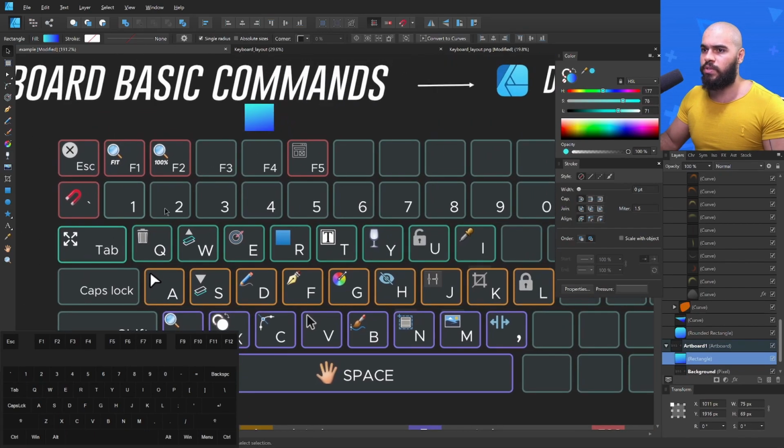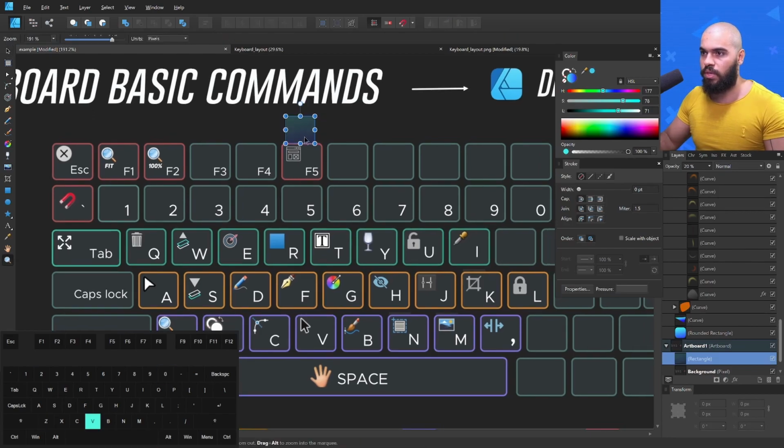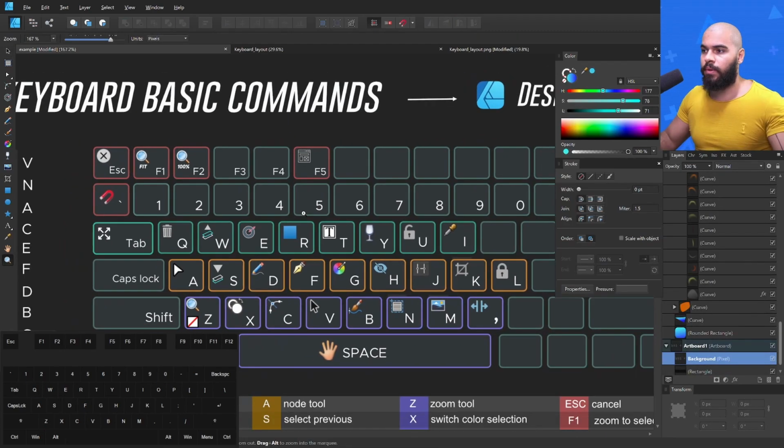Okay, if you press 1 or 2 or 4, it's gonna turn on the opacity. Let's say that you want to set to 50, it's gonna make it 50% opacity. Make sure to keep the layer selected, and then 5 and 0, 50. If you want 100%, 1, 0, 0. If you want 20%, 2, 0. Simple like that. So the numbers work in that way.